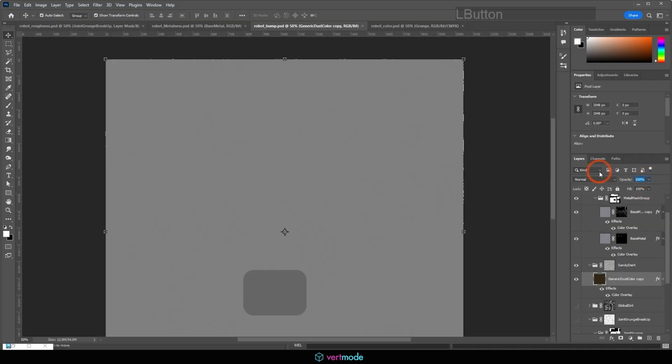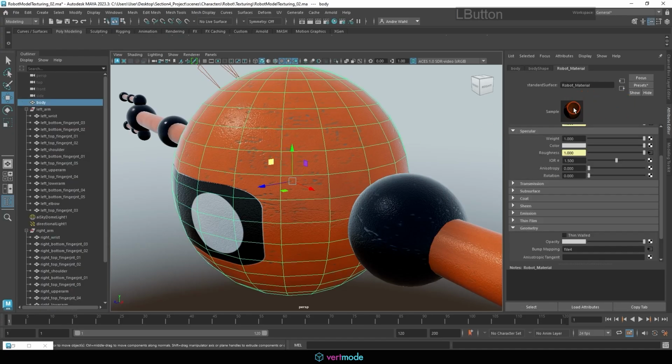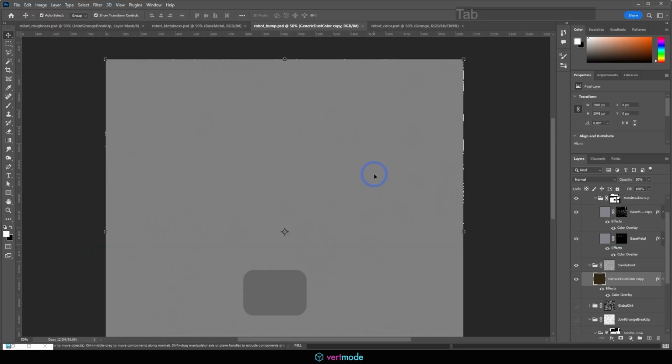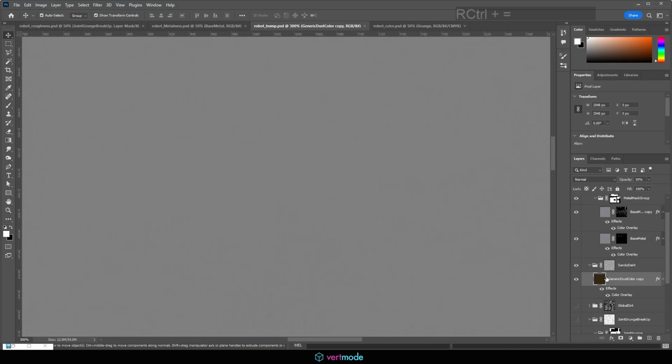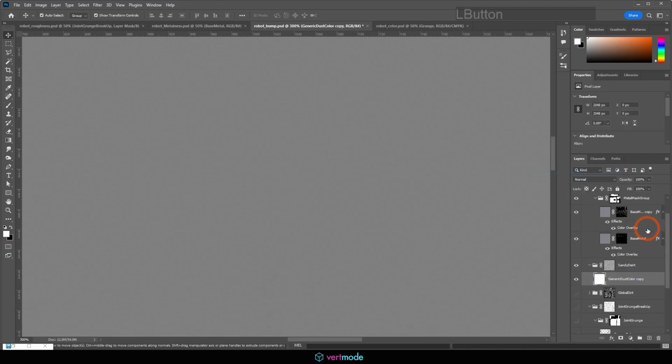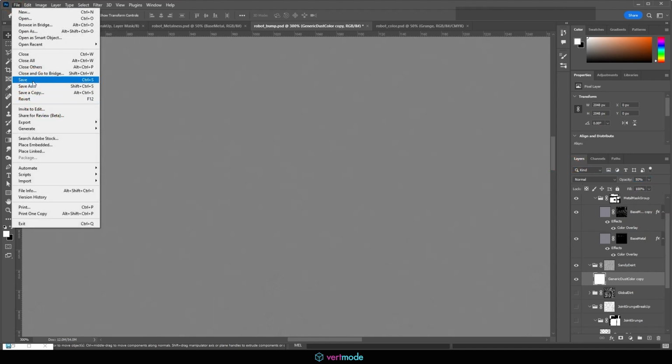I could further do this by making this 1% to 50, and now we're getting into decimals of opacity. So I did 1% on the layer, 50% on the noise. I'm surprised that actually didn't change the way it looks. It could be because I have that color overlay going. Sometimes when you have color overlays, they overwrite things like opacity. If you right-click and do a rasterized layer style, it bakes that down, and then you're not prone to that anymore. So now if I do it, we might see this a bit clearer.